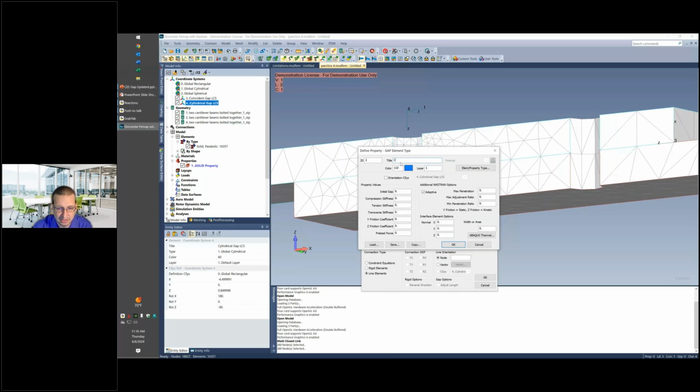We're going to put a value here. We're in the inch unit system here. This is steel. I'm just going to use a value of roughly 1e12. I like to add a small value here in the tension stiffness. Nastran does automatically add one. It's a very small value, I believe somewhere around 1e-14 times this value here, whatever it figures out. And then I'm going to add a matched penetration value here.